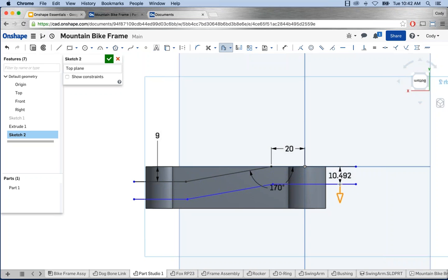So it's very easy to offset all three lines, just left click and drag, and I want an offset of 8mm. Okay. Then we can sketch a few lines to close this contour. Now, again, still not fully defined. I still need to constrain the ends of these.